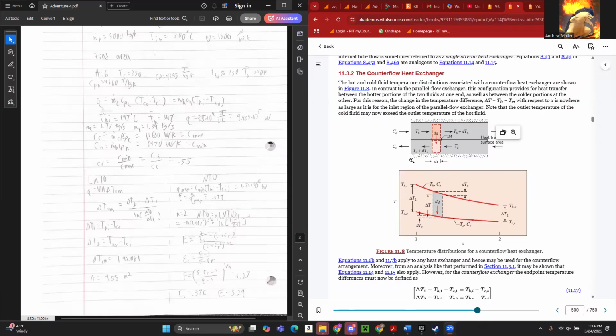So as I mentioned, in more complicated heat exchanger situations, you would need a fudging factor in order to use log mean temperature difference. What this value F would be, you would have to consult a table in order to find it. And what the table looks like is going to be different depending on what exactly the heat exchanger looks like. So even though I forgot the fudging factor, I got 4.55 meters squared for the surface area.